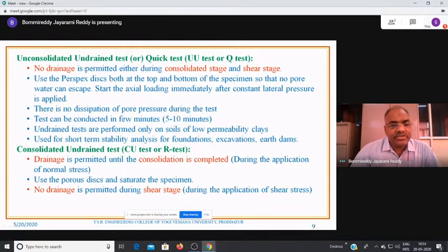Even for principal stresses, the major and minor principal stresses are sigma x plus sigma y by 2 plus or minus half into root of sigma x minus sigma y whole square plus 4 tau square. So the principal stresses are obtained by considering the application of load both in the normal direction and in the shear direction, where shear direction means horizontal, lateral direction.